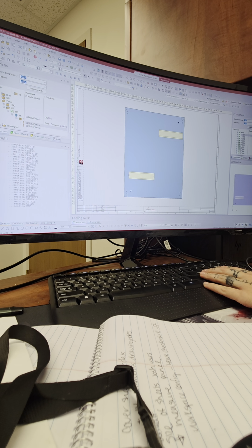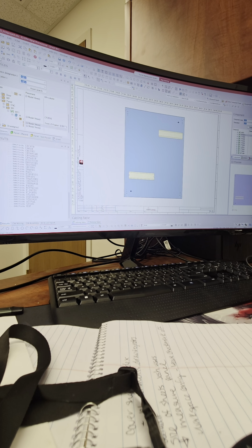But if you select the mounting plate and the item or object and you say align left, now you are, quote unquote, 1 inch from the left. And the same concept with that second number that you have there, that will be the vertical offset. So if you say I want to be 3 inches from the bottom as an example, you can type 3 inches and you say align to bottom, right? So your reference is bottom in this case, but you are 3 inches off, or 3 inches from the bottom. So this is one way of using this placement tool on a quick alignments perspective.